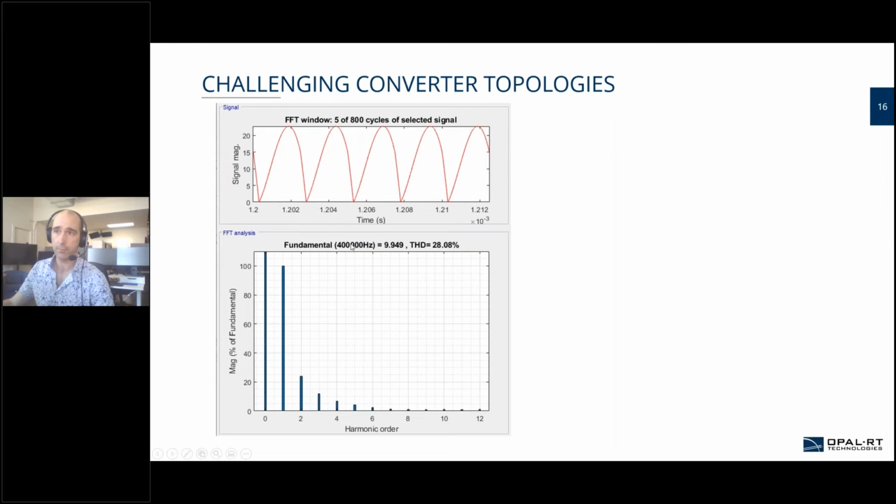So the first thing you have to notice is that the frequency just doubled since we have a dual rectifier. Since we're rectifying, now the frequency just doubled. And if you look at the harmonic content, you have the first harmonic here, but you also have a lot of harmonics that are not negligible: the second, third, fourth, and up to the fifth harmonic I think has to be taken into account. This is because it's not a nice sine wave anymore, but a more complex signal.